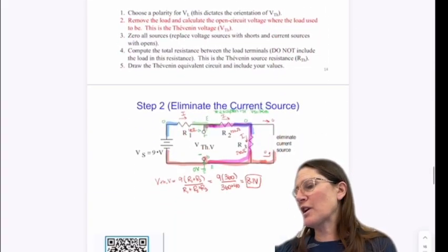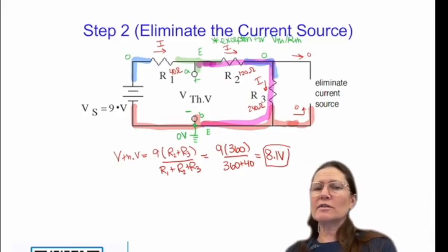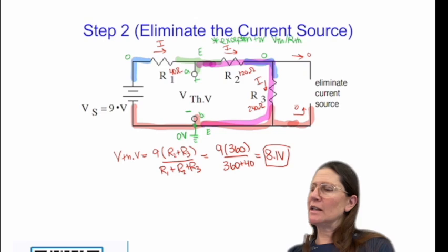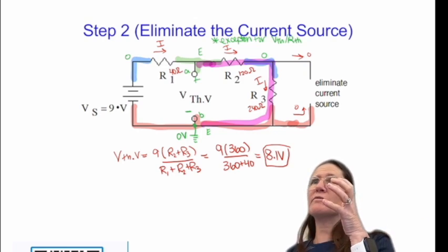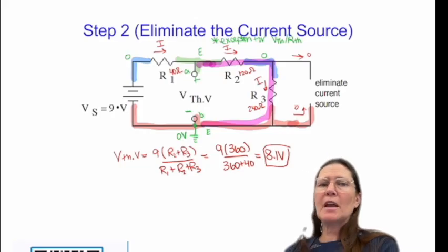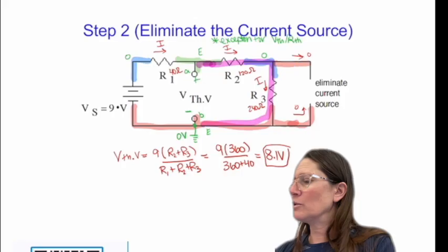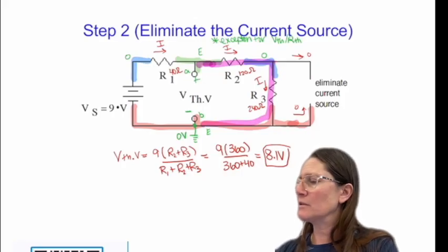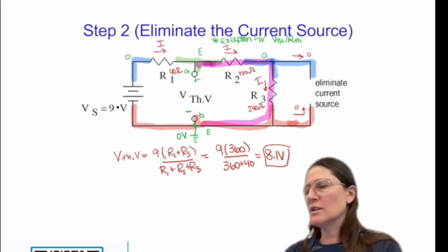Next step was to find the voltage. So did that using superposition. In superposition, then I had to find voltage, you want to zero reference point. So you had to put in the ground. So we added in the ground. And then from there, I noticed it was a voltage divider when I removed the current source. So the voltage divider was across the R2, R3 there.